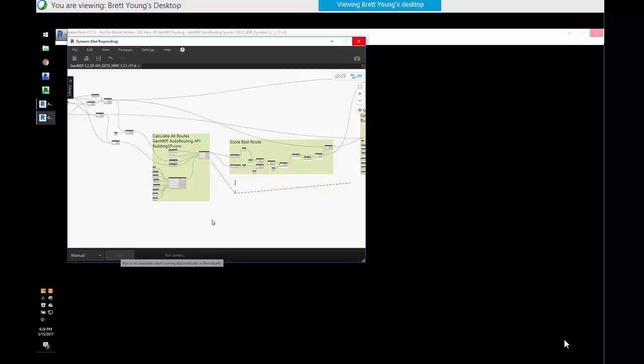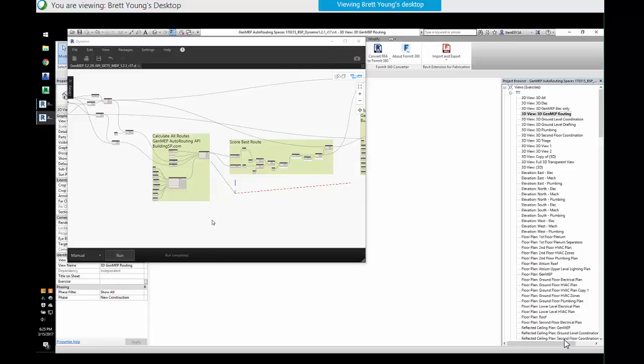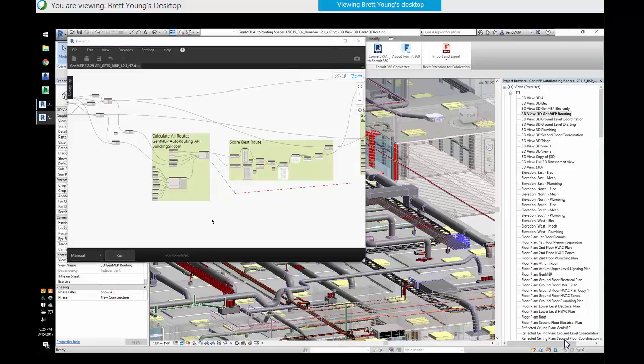So we're running 40 routes from various elevations, sets of 8 that work their way across the building, and we're going to get 5 different sets of scores for which elevation is best, basically. Is this looking for clashes now? It is finding 40 different solutions. They're all clash-free solutions. So we are doing our algorithms through the maze to find 40 different routes, but they're all clash-free, so they all technically can be built, but which is the best way to do it is the question.